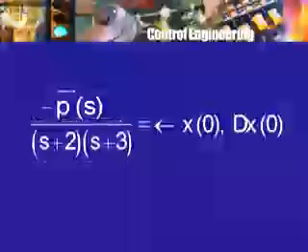That has to be justified because I am looking at a transfer function. I am not just writing some algebraic expression in school algebra and then cancelling a factor. Remember, these are all Laplace transforms of functions. They are not just algebraic expressions, but functions of a complex variable s which arise out of Laplace transformation. So one has to take care, but one can justify the cancellation. And so if I cancel the common factor, the numerator will be of degree 1, the denominator is (s+2)(s+3).